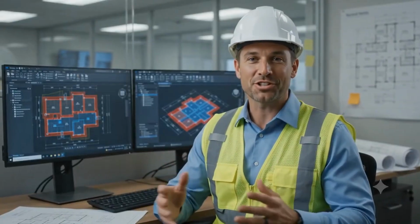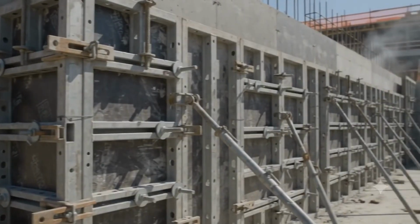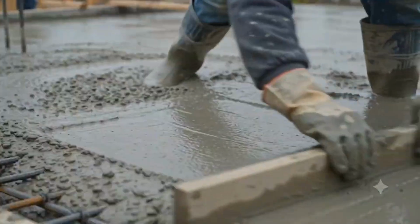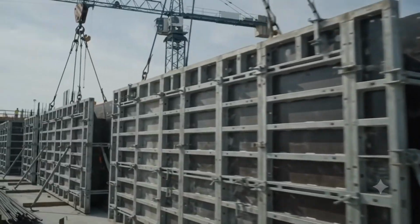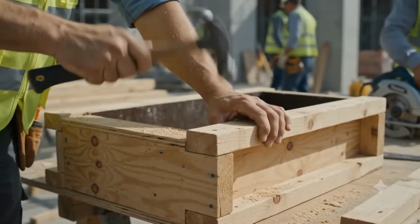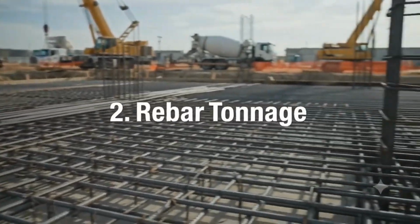Four pillars of a professional Division 03 concrete takeoff: formwork, rebar, mix volume, and placement. Let's break down how to calculate each one step by step. Pillar number 1 is formwork SFCA. Calculate your total surface contact area. Factor in the labor difference between gang forms and timber forms. Pillar number 2 is rebar tonnage.